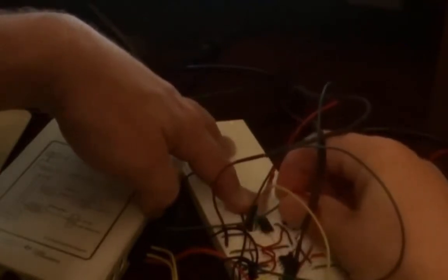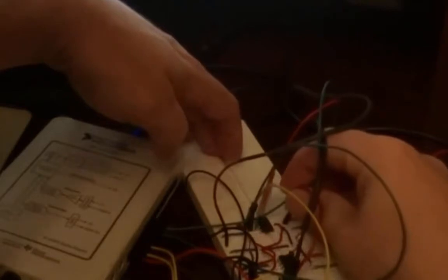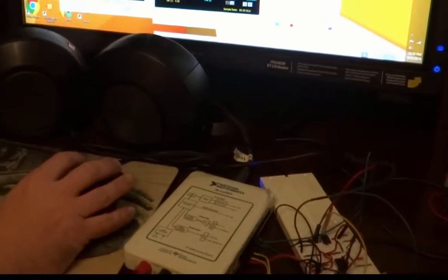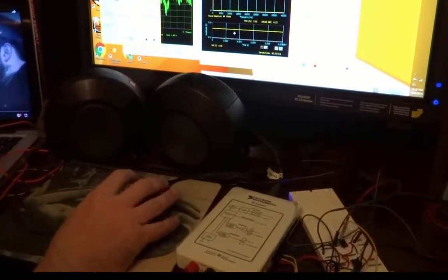Our modulator and our demodulation stage are both being performed by AD633 integrated circuits from Analog Devices. They're high precision modulation circuits. The one on the top here, which we call ICA, is the modulator. The one down at the bottom here, ICB, is the demodulator. And right now, let's listen to the output of the modulation process, and also look at it with the spectrum analyzer here.